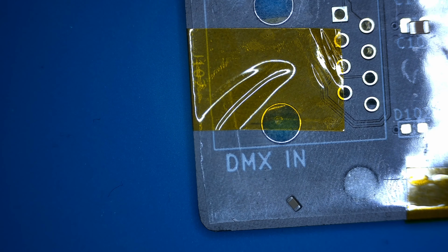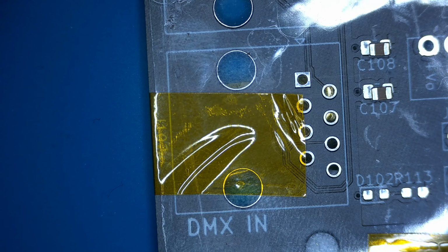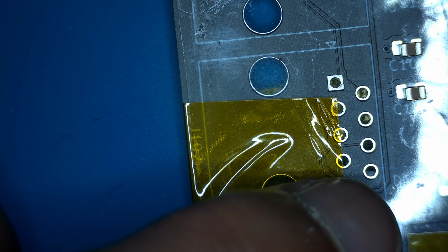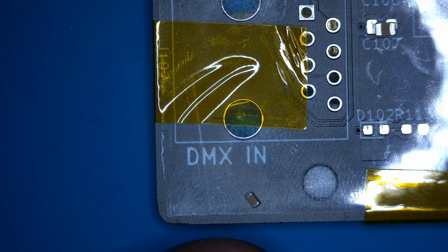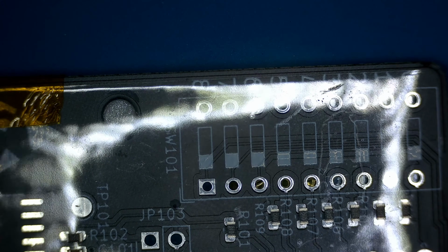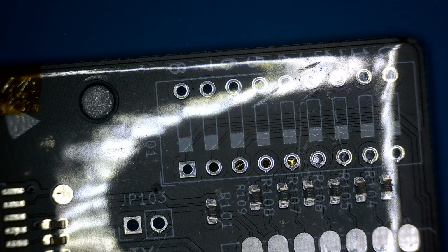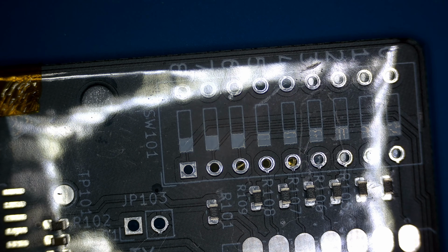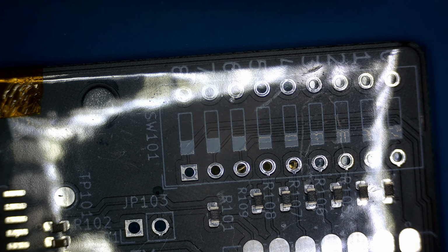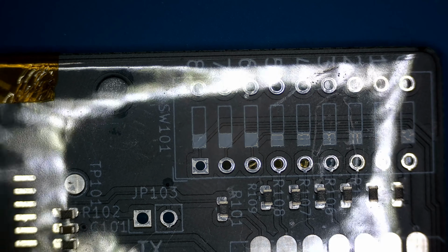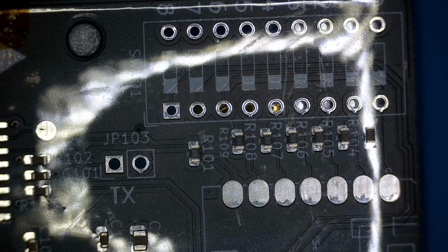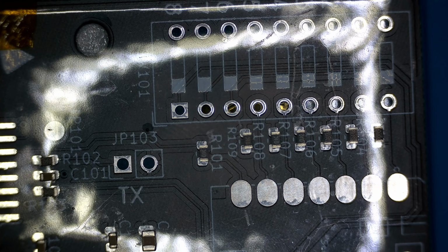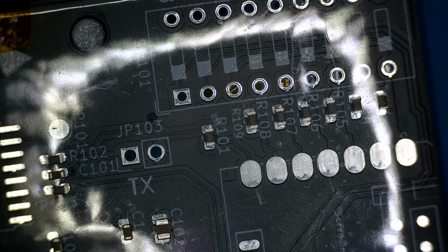Now, if you had a real fiducial and a high contrast pad, something more like that shiny cylindrical pad right there, if we would have keyed off of that, we would have had a much higher chance of success. I probably could have tried to use that one pad of D10 and that upper pad of that switch, and perhaps we would have had better success. I didn't. I was kind of making a point, but you just give it a coordinate and you take a picture. So you can use anything as that fiducial. You just want to make sure they're on opposite ends of the board. So what I'm trying to say here is fiducials matter, and high contrast fiducials matter quite a lot.